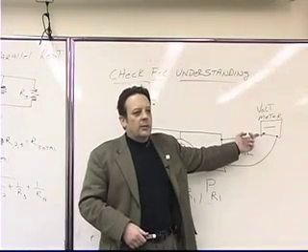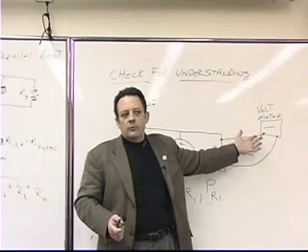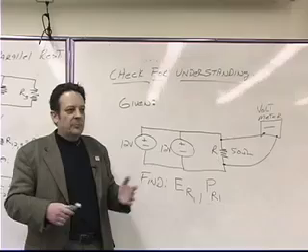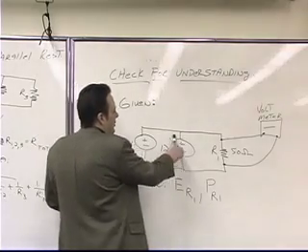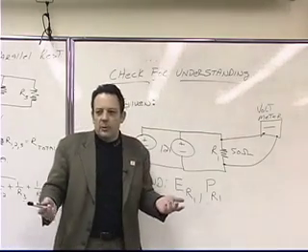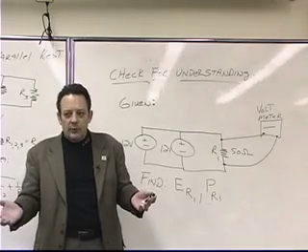What am I going to read on the meter? Okay, why not 24? Because they're in parallel. Very good. When you hook up 2 batteries in parallel with each other, and those of you that have ever done this with an automobile or something, you don't get 24 volts. You still have 12 volts, right?